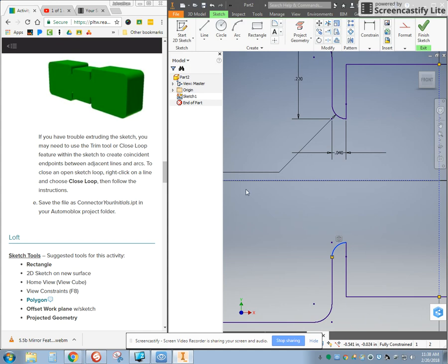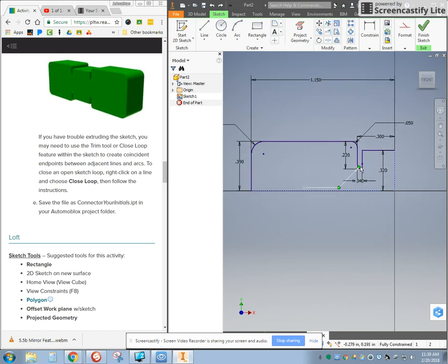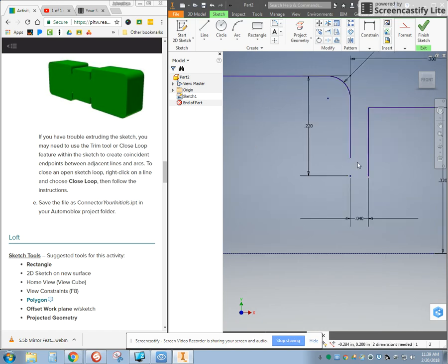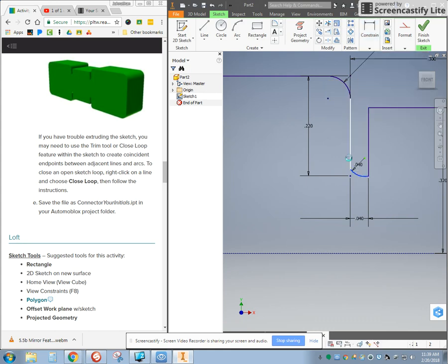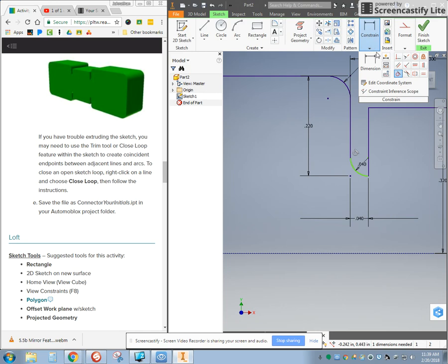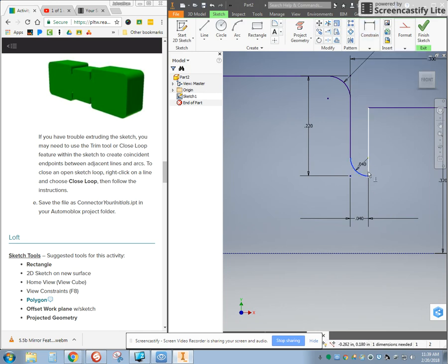What's a little bit easier is if we go back. Now that we don't have any mirrors, instead of doing a fillet for that, what we can do is draw in an arc at 0.04. You'll notice that this arc is able to move around a little bit still. That's because I need to apply some constraints. In this case, a tangent constraint between the arc and the left side. The right side can use a perpendicular constraint. And the last point, this dot, is able to move.